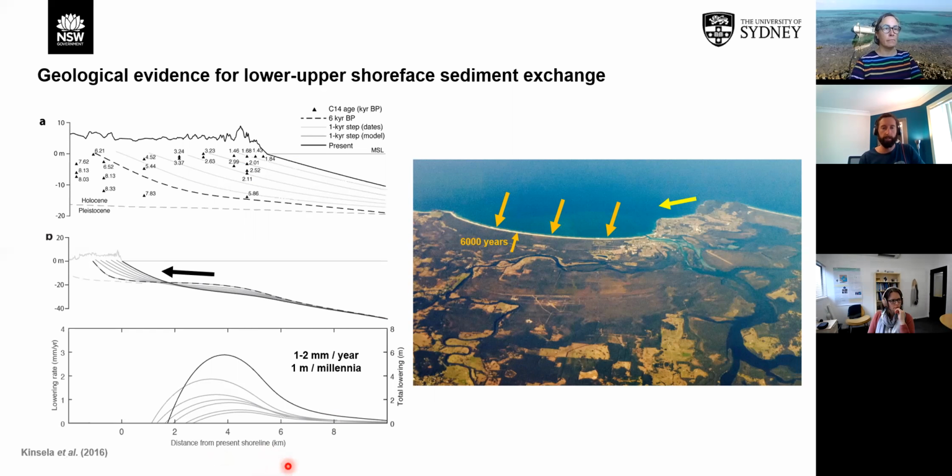What we were able to demonstrate, developing some earlier work of Peter Cowell's, using a slightly different modelling process, was reconstruct through time the process of a disequilibrium overfit shore face lowering through time, and that sediment moving onshore to build out the barrier. What we found here was 80% of the sand came from the shore face offshore and 20% came into the system from around the corner.